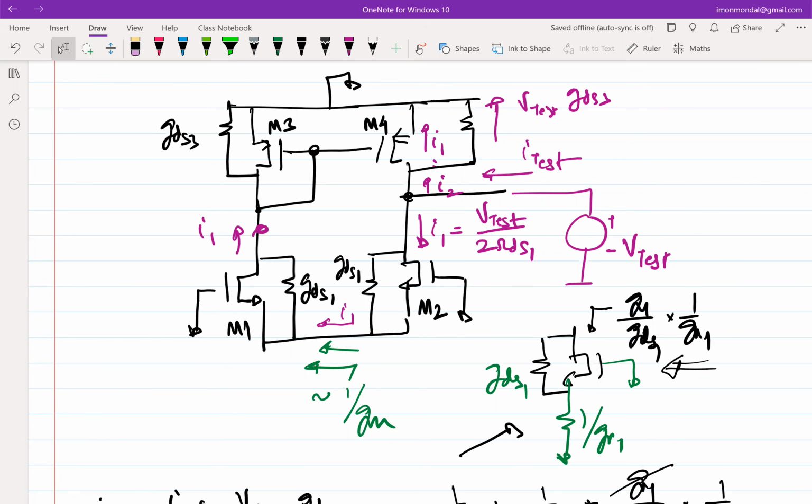But when you do it for the first time, with negative feedback, you'll see that suddenly the GDS of some transistor is much higher. That should trigger that maybe it's not biased properly. A classic case: if you are only concentrating on the small signal parameters and you see GDS is much higher than GM, where it's not supposed to be, then probably it's in the linear region. That's a safe assumption. Then you go back and check the bias points, right? That is one trick that designers often use.